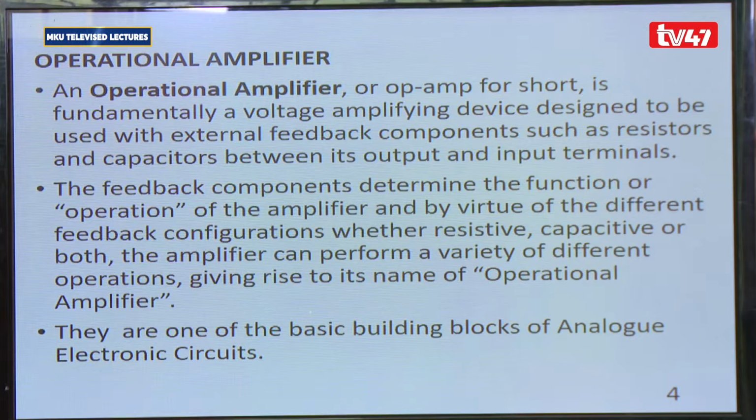We start by defining an operational amplifier. It's usually abbreviated as an op-amp. That is the short form for operational amplifier. It is a fundamentally voltage amplifying device which is designed to be used with some external feedback components such as resistors, capacitors between its output and input terminals.